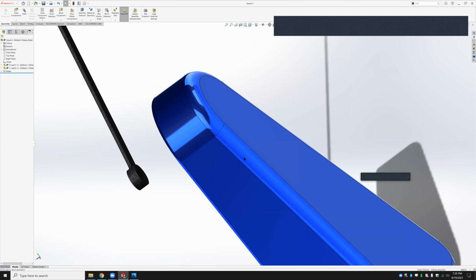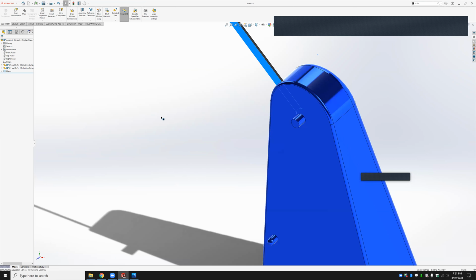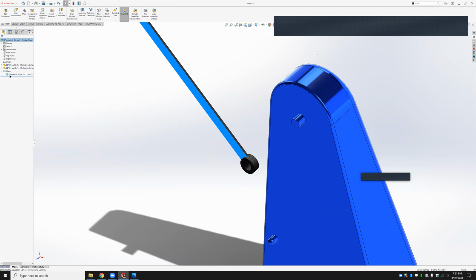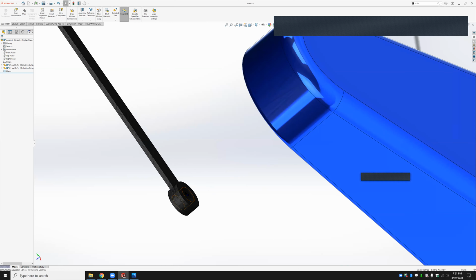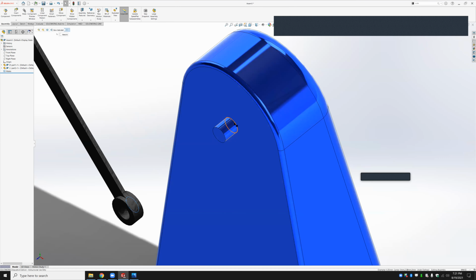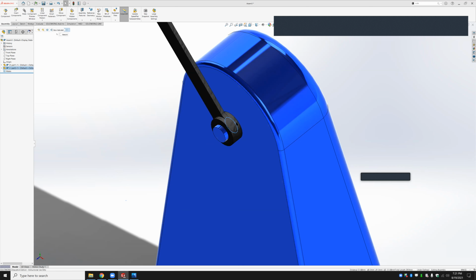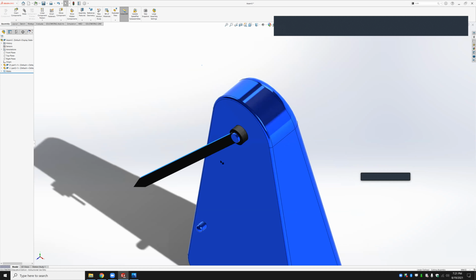Check this out. Usually it's easier on you and easier on SolidWorks if you do as few mates as you can to define what you want. So if you wanted it to be defined like that, you could select this edge right here. Because that is the same diameter as this edge in here, you could do a single coincident mate right there, and you should get the same effect. So your way works and your way is good, but this is just one less mate.